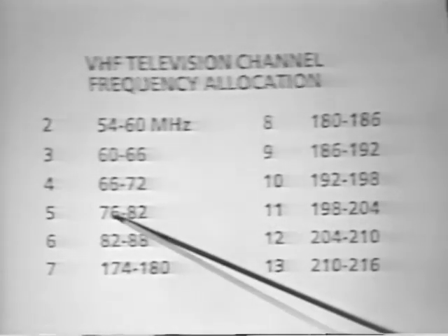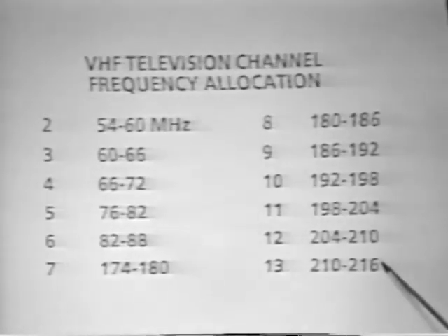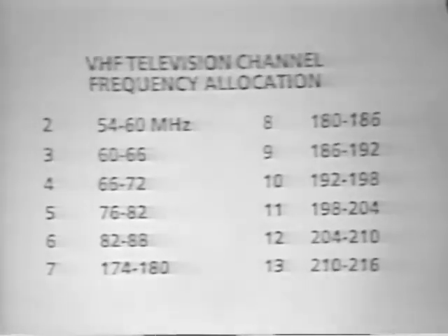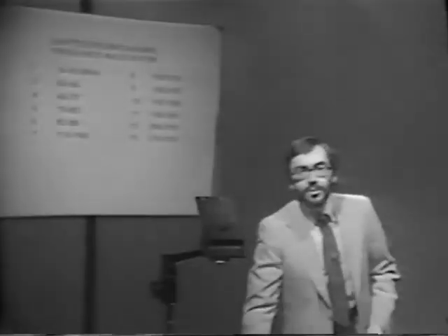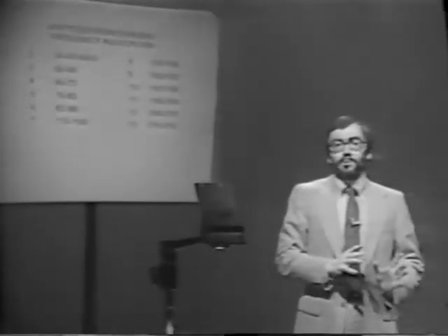Each channel occupies a 6 megahertz bandwidth, but we've put the channels on different portions of the spectrum, and they don't overlap. They're adjacent to each other in these two chunks, and they don't overlap. So this is a very good example of frequency division multiplexing. This can be transmitted over a microwave terrestrial system, a satellite microwave system, or very commonly coaxial cable.